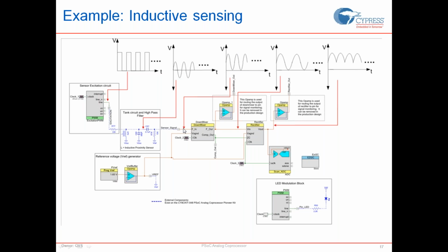So I'm going to be able to see the whole signal using the biasing. And then after I've mixed it using the 8 megahertz, I get an 83 kilohertz signal, which is a much slower frequency than the input to the mixer. And the output of the rectifier is similar to a full wave rectifier. I get a full wave rectified output, which is measured by the ADC.